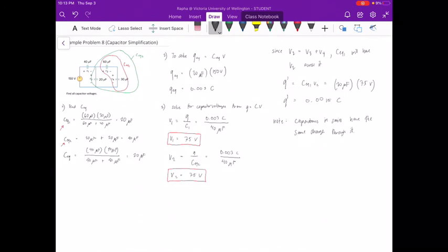So it's basically saying that in a series connection, if it were resistors in a series connection, the current is equal all throughout. The same concept is true for capacitance, only that it deals with charge, and capacitance in series will have the same charge through it, which means that we can solve for V3 and V4 for the 60 microfarad and 30 microfarad capacitors in the circuit diagram using Q apostrophe.